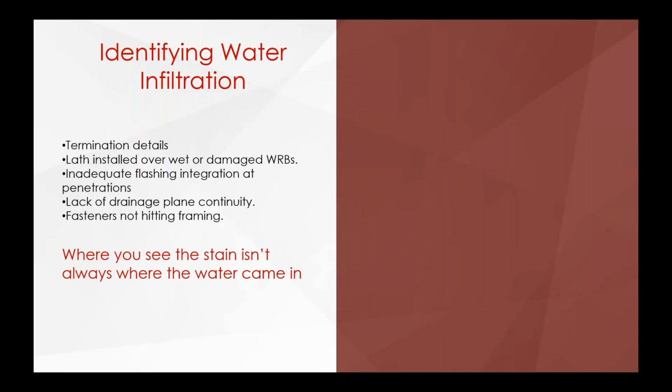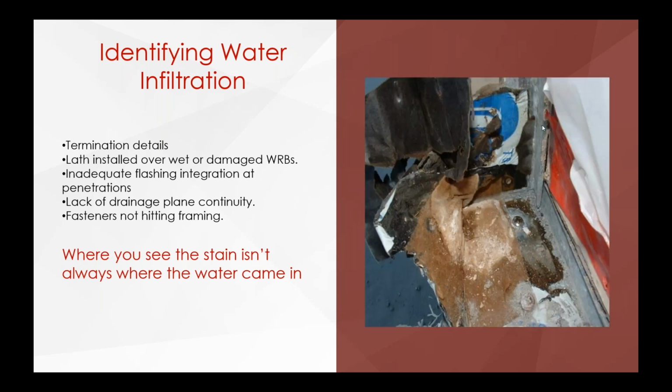One of the things we want to do is identify where the water infiltration is coming from. I had a general rule when I would go out to the fields and I was doing leak detection, and there's specific places that I would be looking at. And I got some of the photos in here. So here, what you see is a flat recessed window. Issues with that already. It should have been sloped. However, once you pull everything back, you see that the self-adhered flashing stuck in certain areas and certain areas not too good. On top of that, they used a perforated casing bead. And as you could see from this, water can get in through those holes.